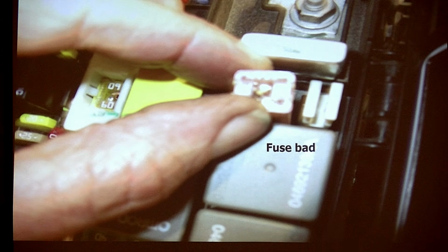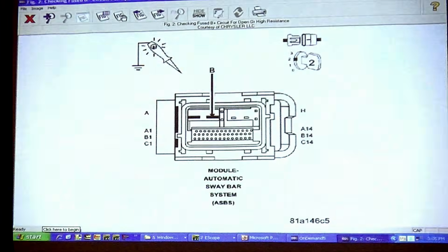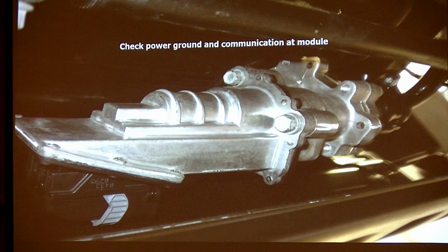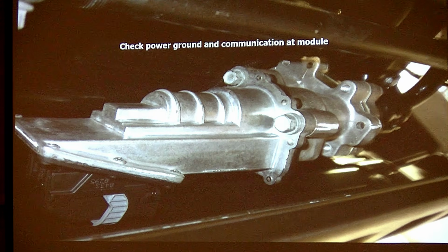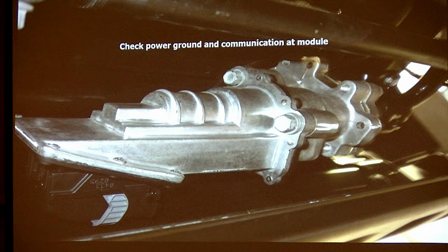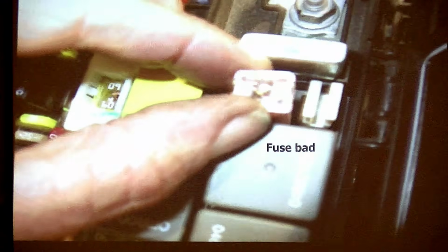But what am I going to check first before I do all that? The easy stuff. Power and ground. Don't I have a power and ground schematic right there? Well, at least I know I can check that. And you know that the power and ground's got to be big, because that thing is bending that sway bar. And you ain't bending no sway bar without having a lot of current on it, right? So the power and ground on this dude, he's the big wires.